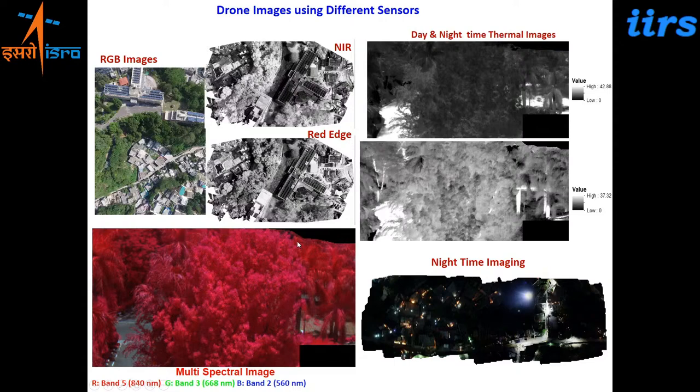We have one of the studies which we did in moderate terrain, which has small hillocks plus agriculture, orchards, and a different range of land use. Small built-up areas were there. A fixed wing drone was used for this application. We flew the drone at variable altitudes to see how much accuracy we can get for the topographic or terrain parameters.